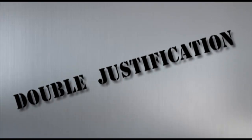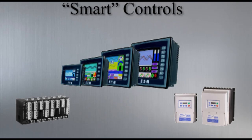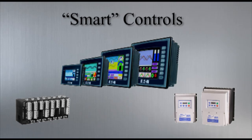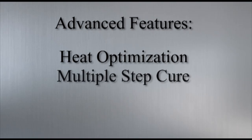But there's more. This is what I like to call double justification. The heat injector system uses the same state-of-the-art technology that produced the energy savings to perform some advanced features. For example, heat optimization. This feature modulates airflow so the desired air temperature can be achieved even on the coldest of days. Multiple step cure. This feature allows the operator to set multiple times, temperatures, and airflows for the curing process.